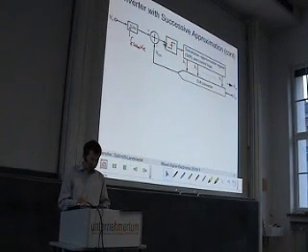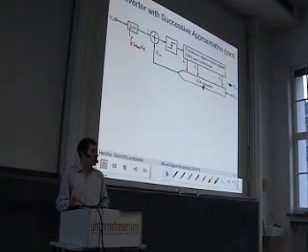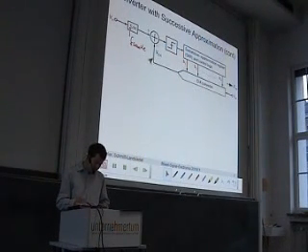So here we check whether the input signal is larger or less than the internal signal. And depending on this, we either increment the output voltage of the DAC or we decrement the output voltage of the DAC. Then we have a new DAC voltage.